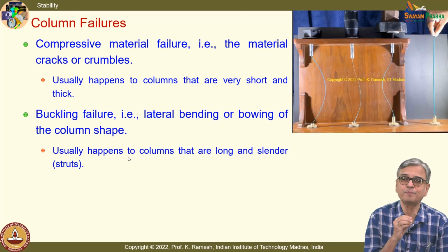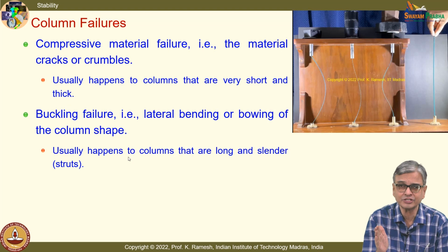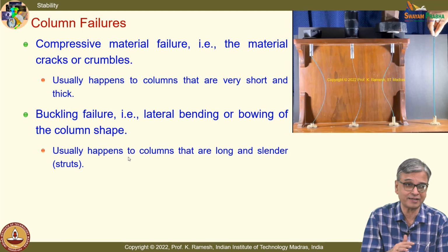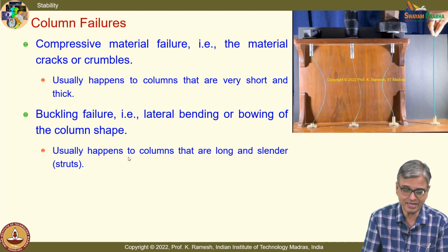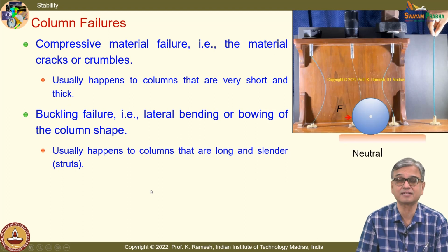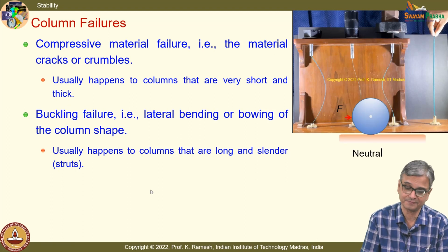Okay. So, what people have done is, they have done the mathematical analysis and also based on experience, they find there is a load which is labeled as a critical load, beyond which if there is any lateral disturbance, even a small disturbance, it will go into buckled shape. The load by itself does not introduce buckling if there is no disturbance. Okay. Now, the question is, from where the disturbance comes, that also has to be looked at.